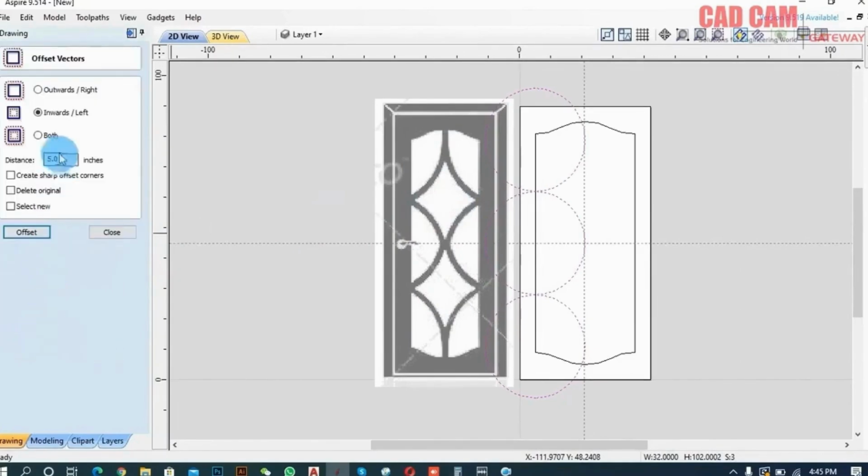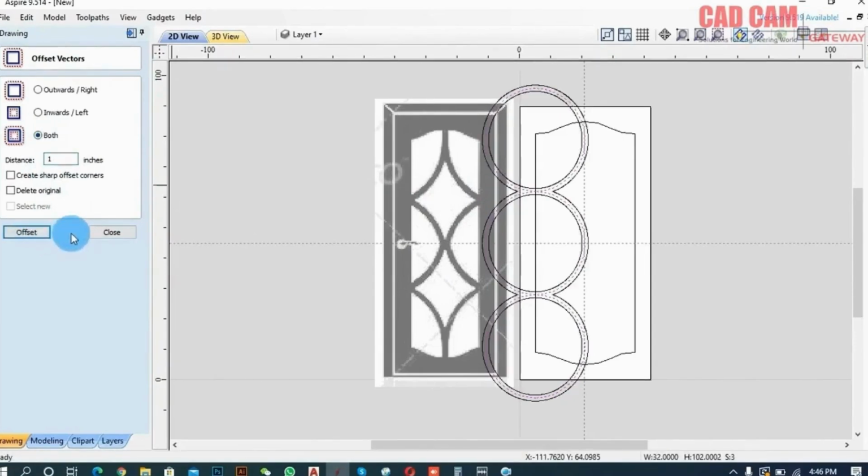I use the offset command and it is very precise, meaning I will use these circles as a center line. And beyond that, I will offset the object. This strip in the middle is a 2-inch strip, so I told it to offset 1 inch on the inside and 1 inch on the outside, meaning on both sides. As soon as I offset it, we have to mirror this thing forward.